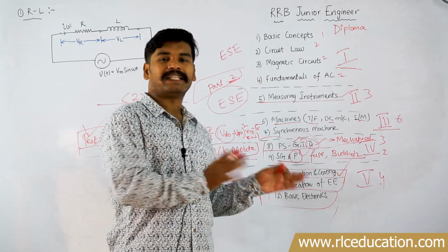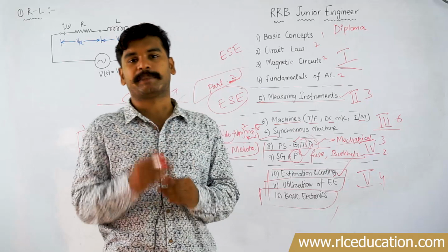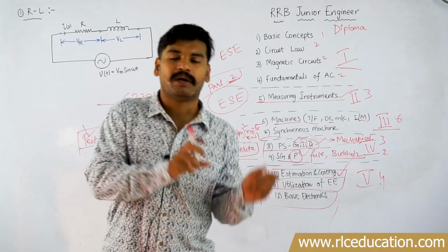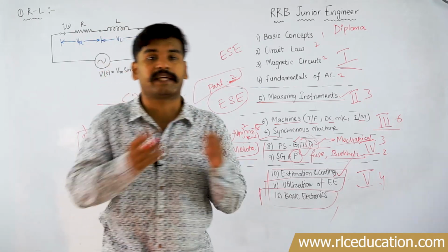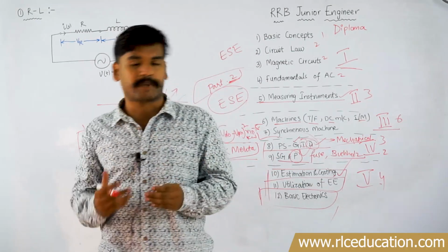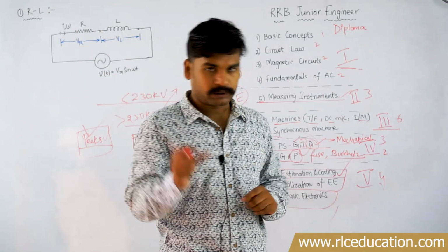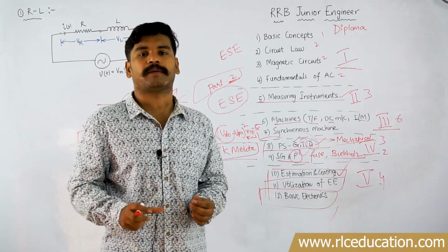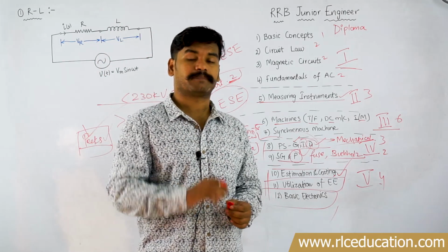Nothing else is there, just some basics of EDC. You have to study some basic semiconductor physics, and the diode, its construction, doping levels, what are p-type, n-type impurities, such kind of things. Again, different types of diodes like Zener diode, what are the different modes of breakdown, avalanche, Zener breakdown, and different types of diodes, tunnel diode, Schottky diode. What are the applications of those diodes? What is the speciality of those diodes? You should be clear about each and every type of diode, photodiode, etc. And again, some basic diode based circuits.